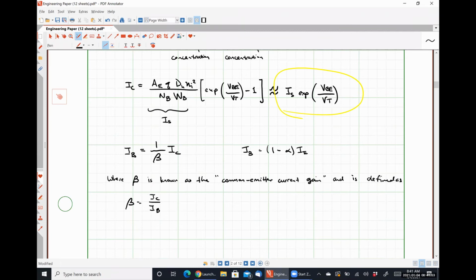Let's see, beta, I gotta leave myself some room here. It typically ranges on the order of 10 to 100, could be higher, might be a little less. High power applications is typically a little bit less than this range, but typically speaking, somewhere in the 10 to 100 range is reasonable. If you go onto a data sheet for a BJT transistor, you're never explicitly told beta.